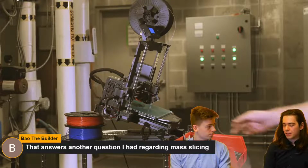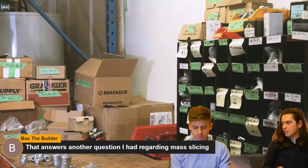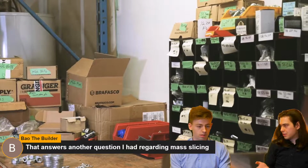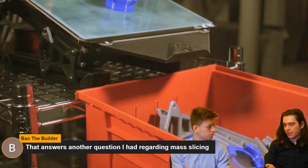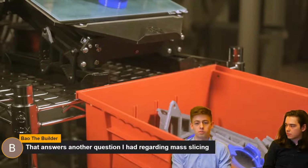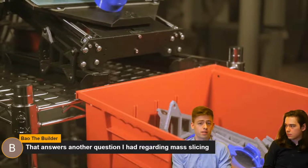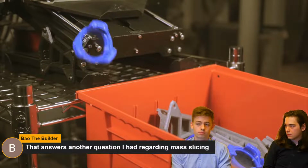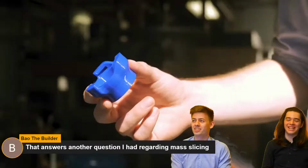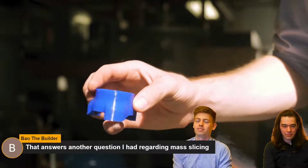We should probably talk about the other settings, because I hadn't even thought about X, Y offsets, but that's an easy one to do. And since we already do G-code file processing, we could even do complicated things like speeds, maybe. Yeah, we could do speed. There's a G-code for just percentage speed. If there's a machine that can handle better or faster speeds or accelerations, or even maybe different filament diameters, I hope you're not, but if you are, maybe you could change that. No, actually, your printer would know because it's E-steps. So that's fine. That would work.